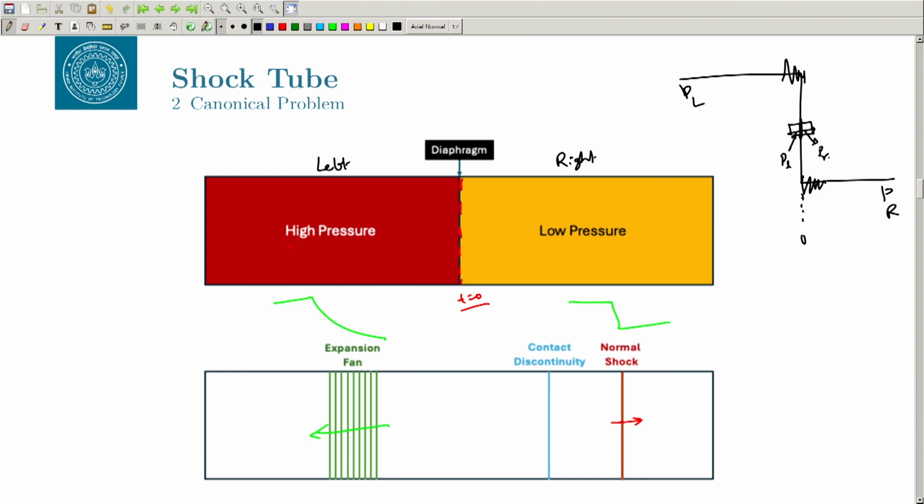The shock may be happening in a very small region, but what your numerical scheme will do is smear this out, and then your shock is happening in this thick region, let us say between these lines, and then it can try to predict the shock like this. Now, the catch is if you smear it out too much, which we will see, let us say, in the Lax-Friedrichs scheme, which has very high dissipation, your shock will look like this. That is not what we want, right. It has completely dissipated the shock, and you are getting something very different. It looks like a continuous shock.